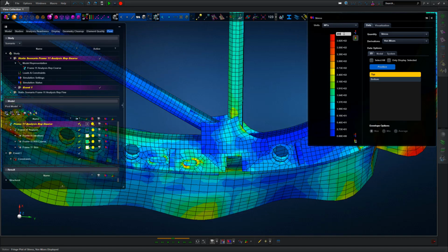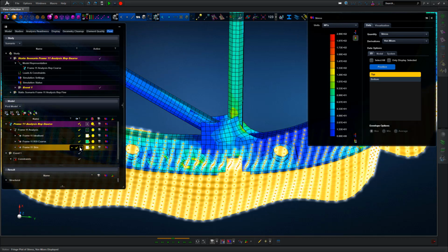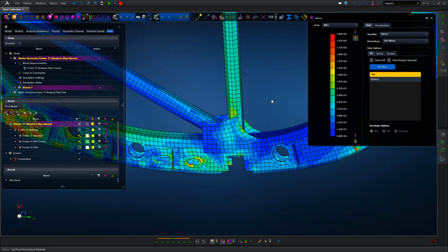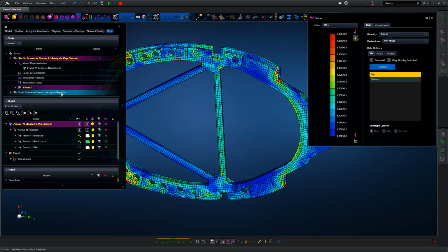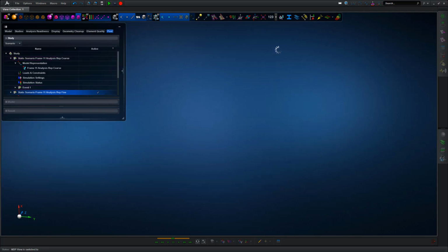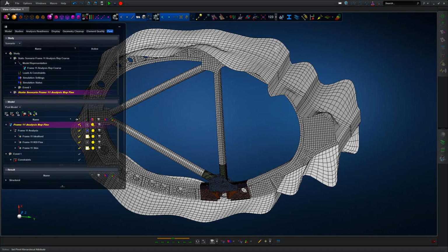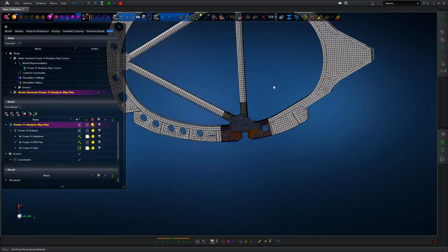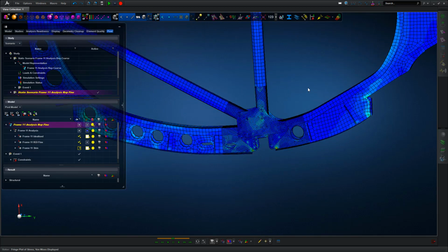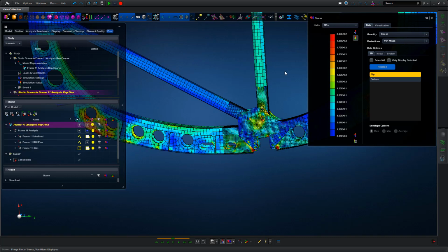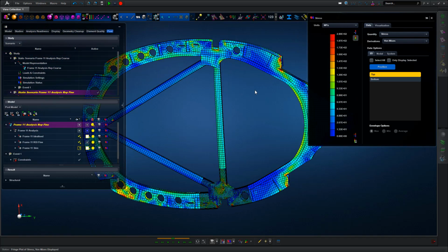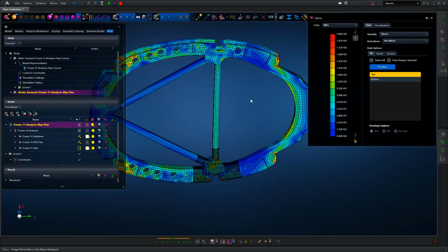taking the skin out of view and setting the extreme stress limit to 200 MPa, and we can see the fringe that's developed at that level. And then we can repeat that, so we can simply double click and change the representation output type to the finer model, and taking the skin out of view, we can look at the von Mises stress, again setting the limit to 200 MPa, so we've got a like for like comparison, and we can see the change in overall model response.